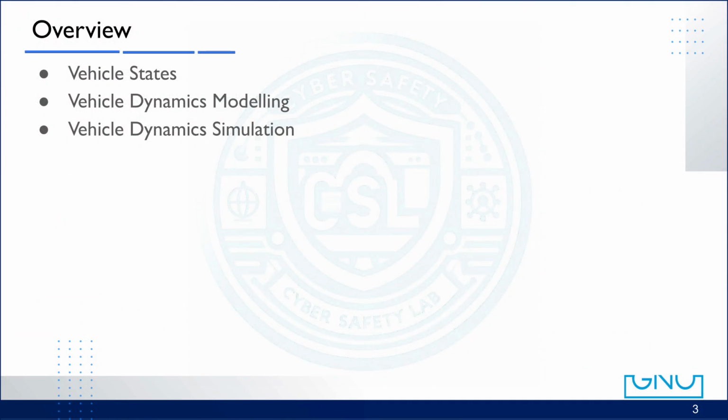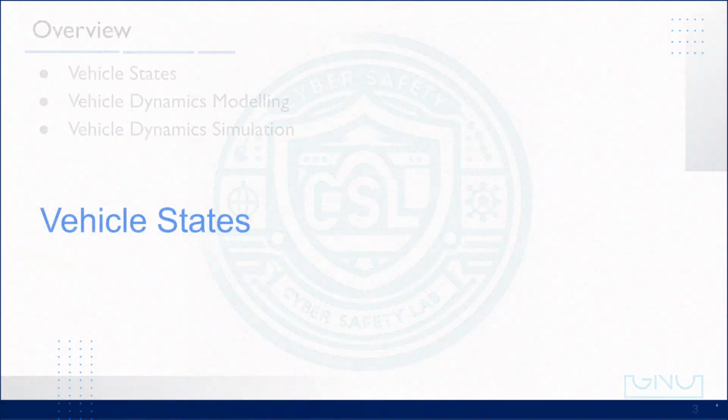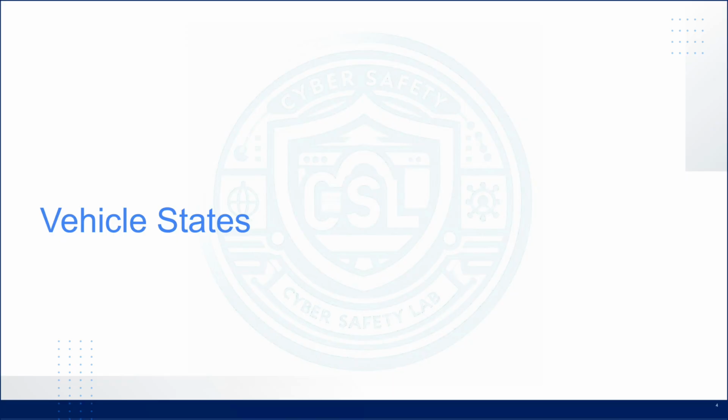Let's begin with an overview of today's lecture. We'll first discuss vehicle states, which describe how we mathematically represent a car's motion, things like position, velocity, and orientation. Next, we'll move on to vehicle dynamics modeling, where we express how control inputs, such as steering or acceleration, cause changes in those states. Finally, we'll talk about vehicle dynamics simulation, showing how these models can be used in practice to predict and visualize vehicle motion. Now let's begin with the concept of vehicle states.